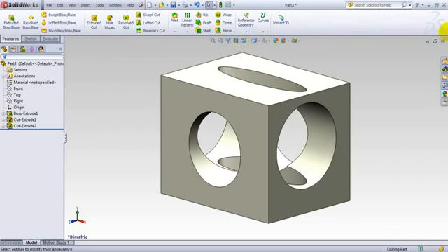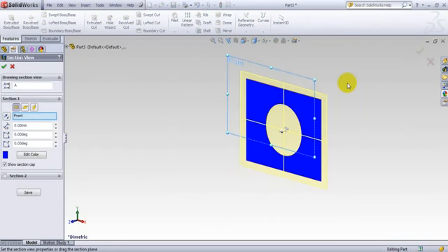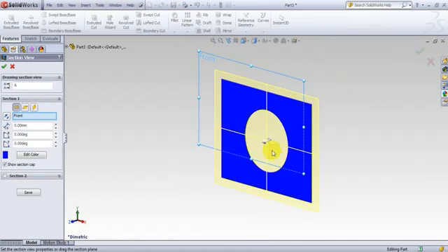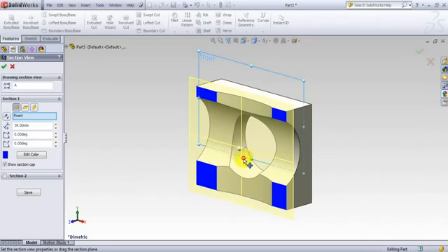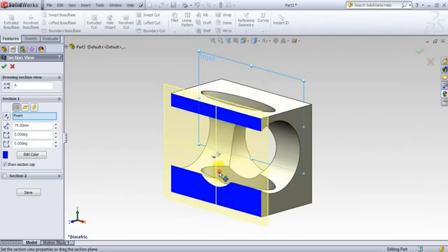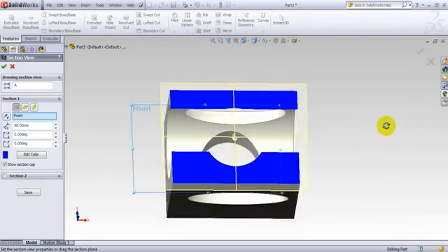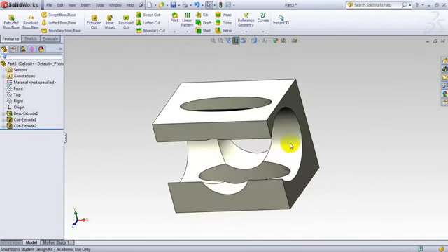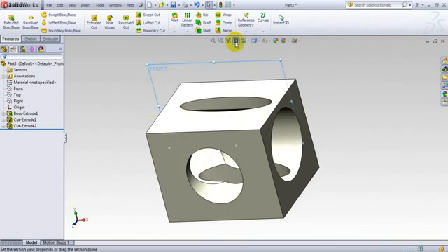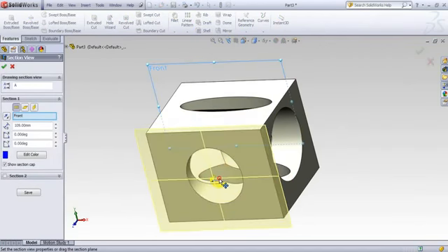And now there is another feature which is very handy. It is this particular sectioning view, and what you do is click on it, and it sections it for you. So I start from the far end, and as I left click and drag this, it draws the whole thing for me with a different sectioning. And if I want to stop right there, this is my sectioning here, and I can continue a different sectioning from here.